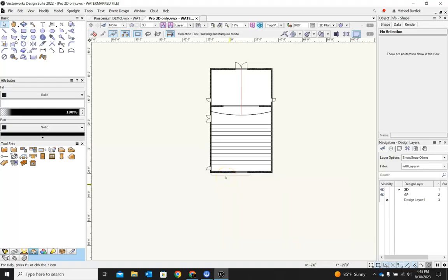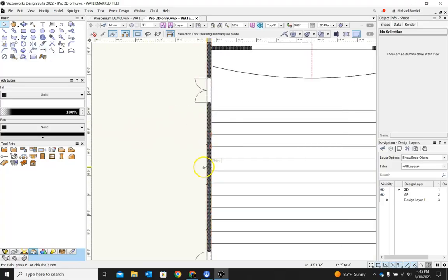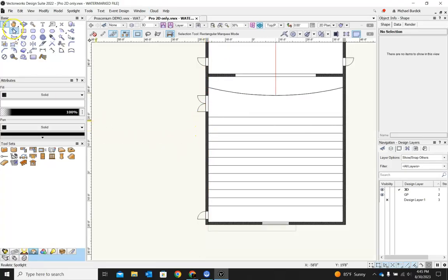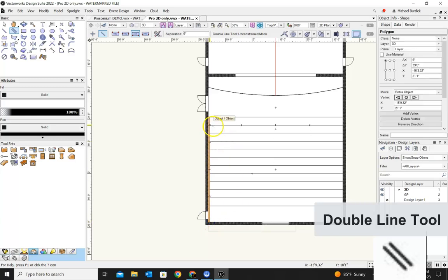The other option would be to actually create a shape on its side that has the correct profile and then flop it down. Let me show you exactly what I mean, because it's a little heady. So we know all of our steps are 6 inches high, and they step up as we move from step to step. So what I'm going to do is make this 6 inches. So I'm going to build the profile along here. I'm just going to run 6 inches there.